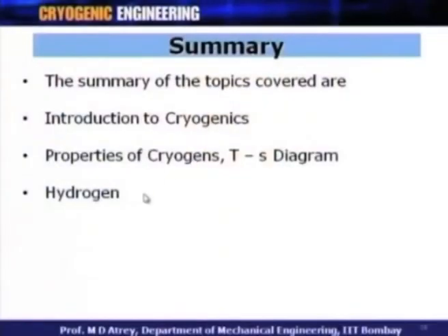We talked about hydrogen and the importance of the ortho and para forms of hydrogen. We talked about the conversion of ortho to para as we go on reducing the temperature of hydrogen. We talked about the liquefaction of hydrogen and the necessary condition that complete ortho to para transformation should take place during liquefaction. Otherwise, all the liquid which is generated will get evaporated, because ortho to para conversion is an exothermic process.